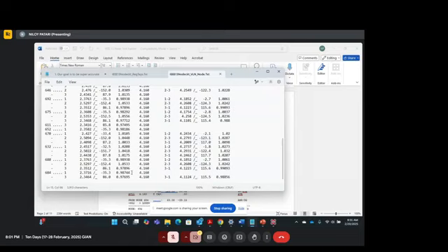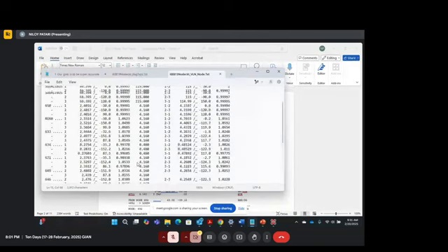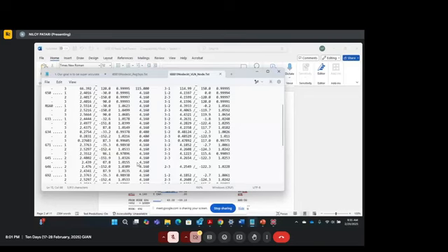And if the power flow matches with the meter data, obviously the conditions have to be exactly the same, loads have to be exactly the same, configurations have to be exactly the same. Under those situations, if the power flow results match with the meter data, it won't match exactly, but if it matches closely, then you can say that your model is correct. So this model looks correct as for now because the voltages are pretty close, right? This is the kind of validation that you should do.